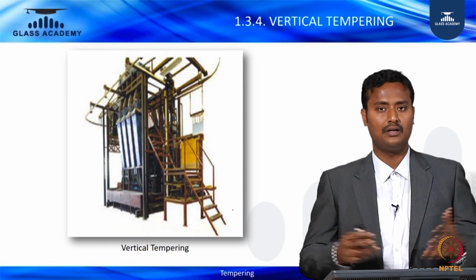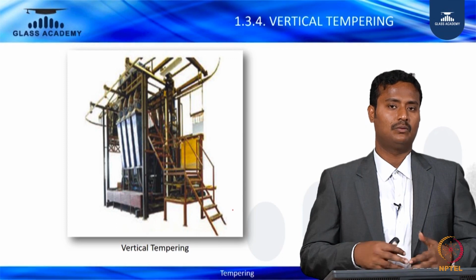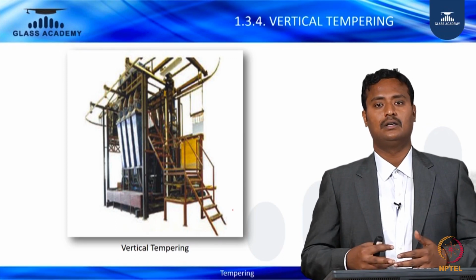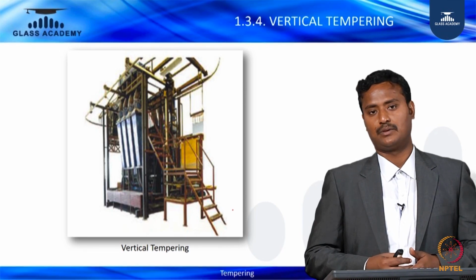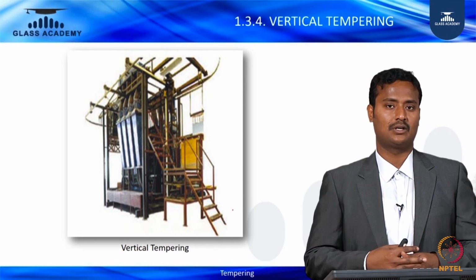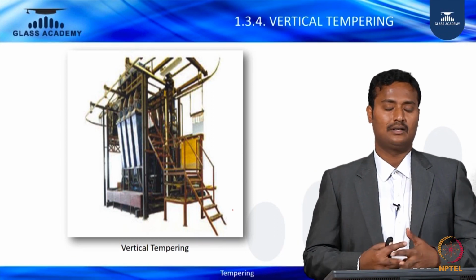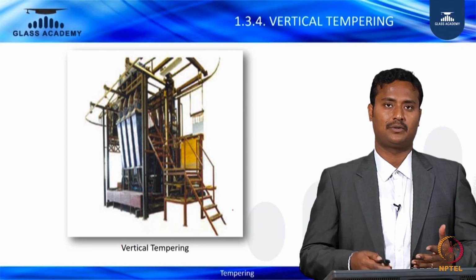So it is not commonly used for what you are seeing, the architectural glasses, which are not processed with the help of vertical tempering. Whatever architectural glasses you are seeing are completely from the horizontal tempering process, not from vertical tempering.